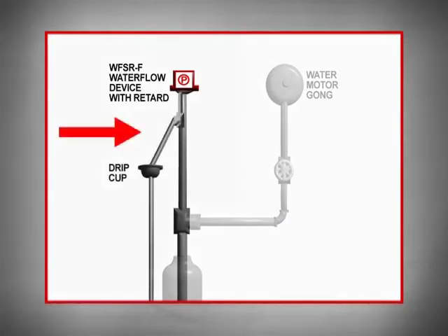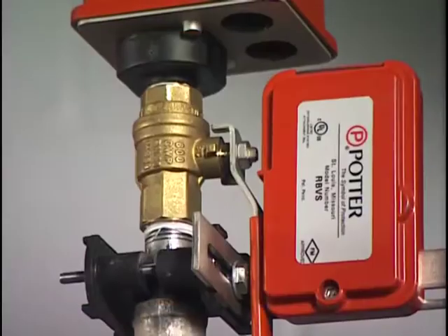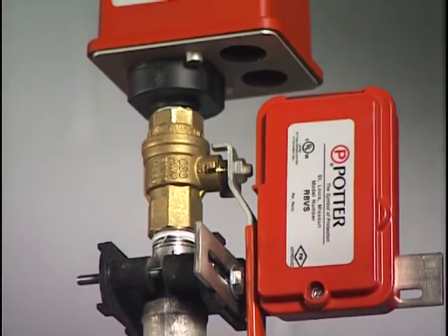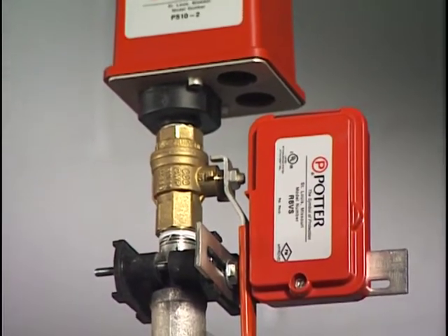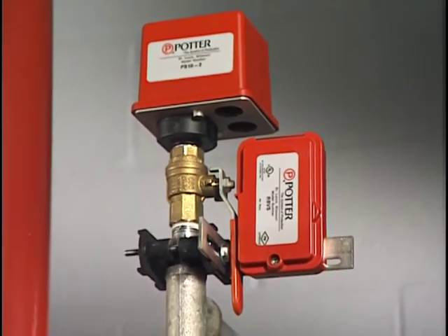However, an automatic drain is still required with this type of monitoring in order to relieve the pressure on the line. Pressure-type flow switches must be installed in the line before any shutoff valve, or the shutoff valve must be monitored by a supervisory switch.